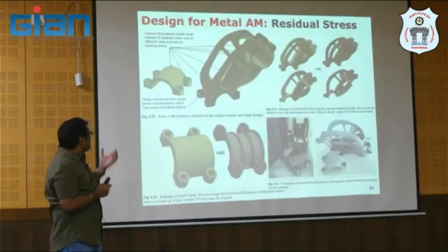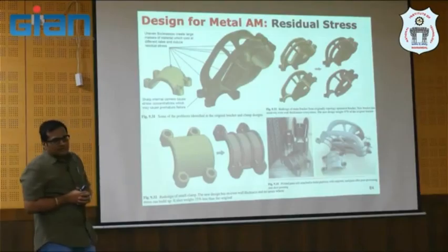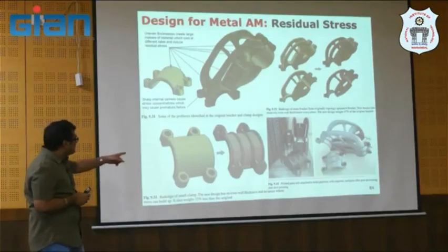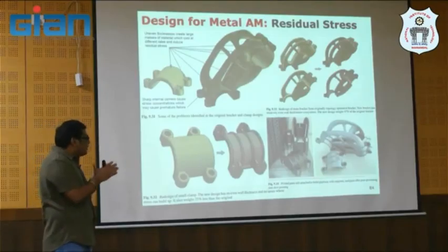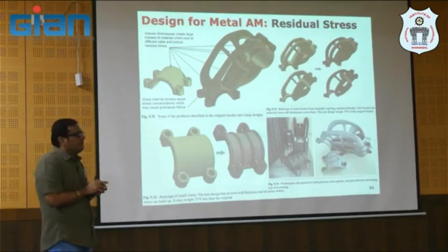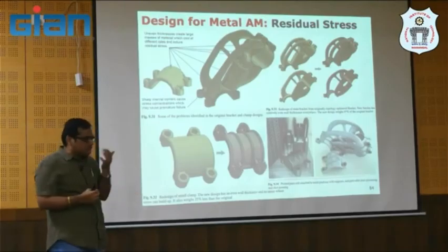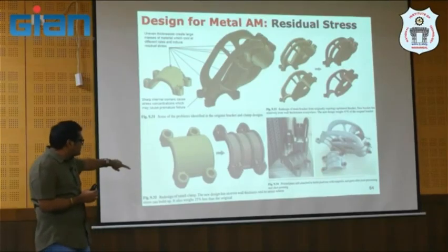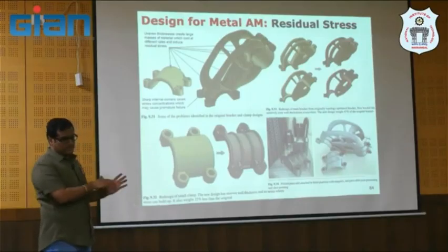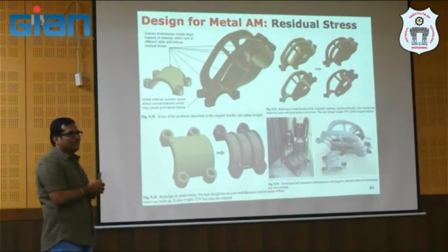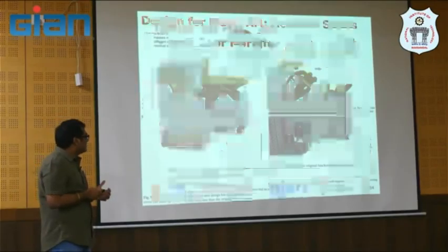And another one is uneven thickness of these features, which we can see. So you follow the thumb rule, unlike your injection molding also, where we have some thumb rules which we need to follow here also. Always use a uniform thickness, but not varying thicknesses. Maybe again it will create a problem here, right?